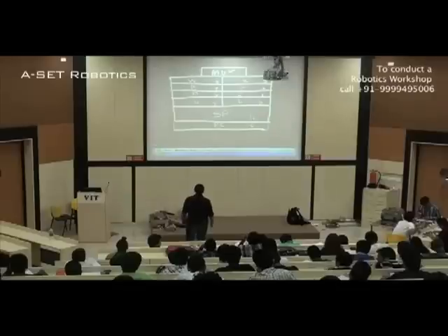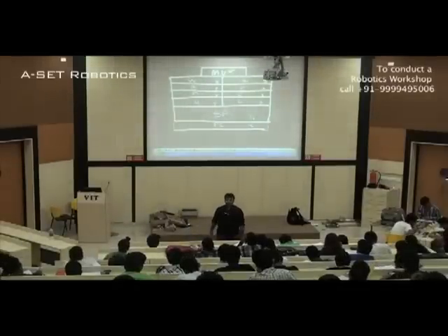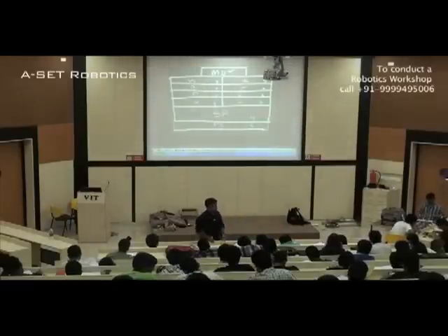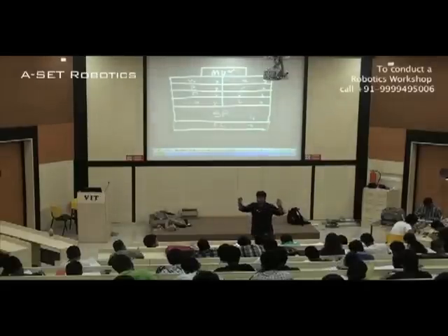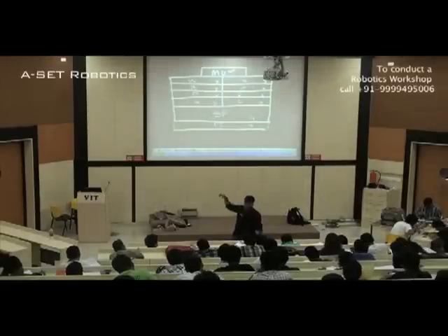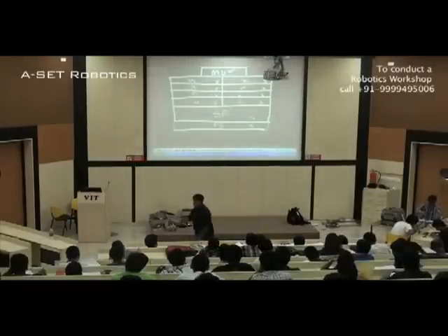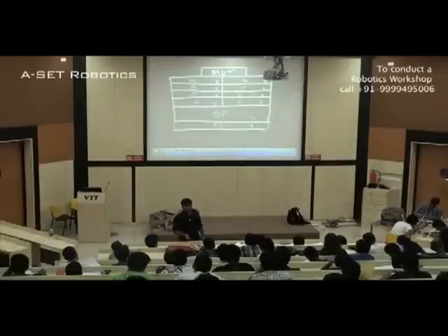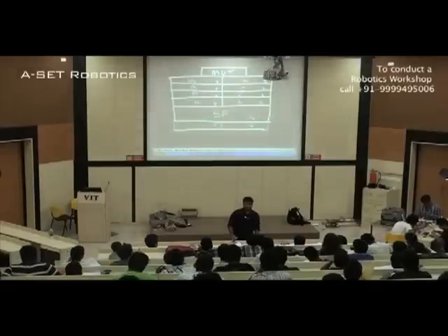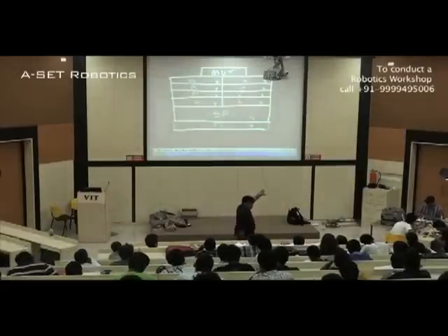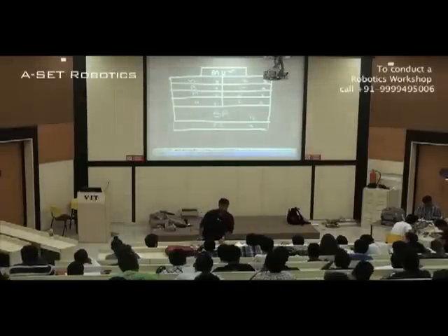WZ, BC, DE and HL can be accessed by the programmer. These are of 8 bits, and these registers can be used in pairs, like W and Z can be combined together to make a 16-bit register. HL, which we generally call high and low, can again act as a single register, and so can DE. So if we store 8 bits first and then 8 bits after that, it becomes 16 bits and we can address a 16-bit memory location. This is how it works.